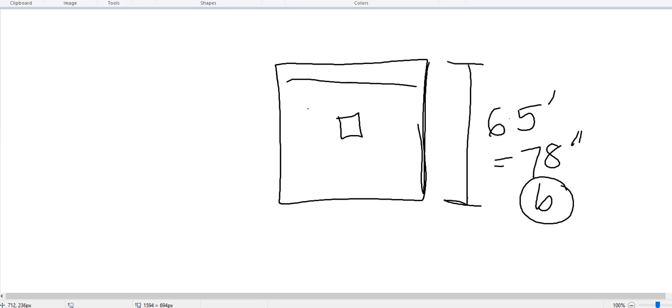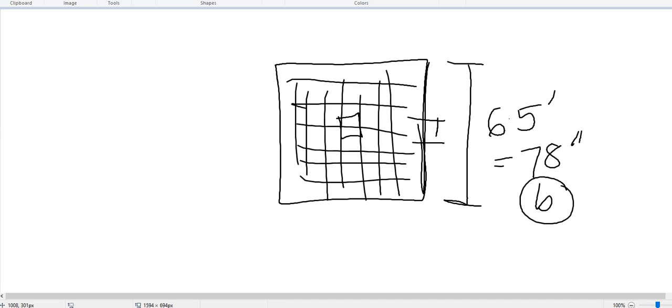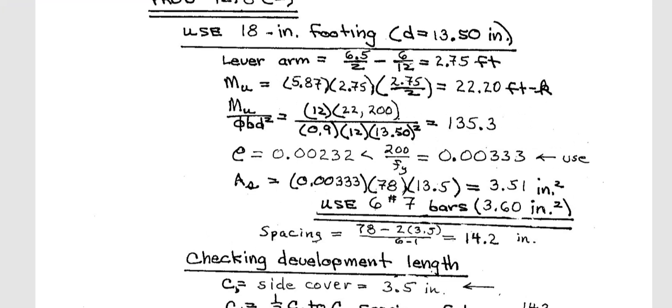That means whatever the reinforcement you need to place here, and as it is square, both way it is same. This time they are taking entire width. If you take a 12 inch strip, it will be okay. Whatever you get as reinforcement here, you have to copy paste all around. That is the concept. Okay, so they used the entire 78 and d.